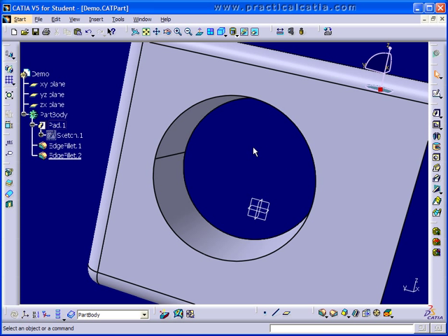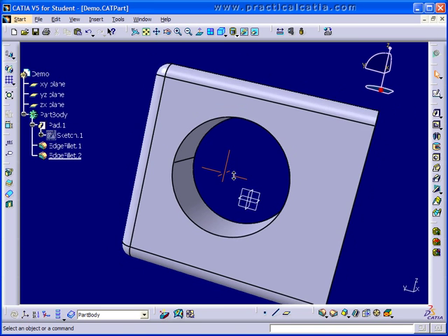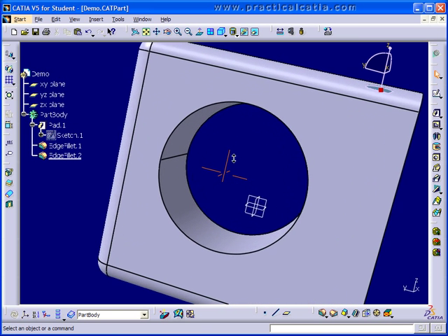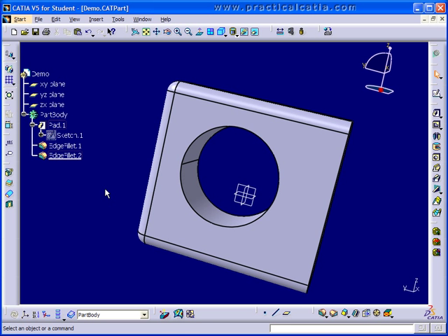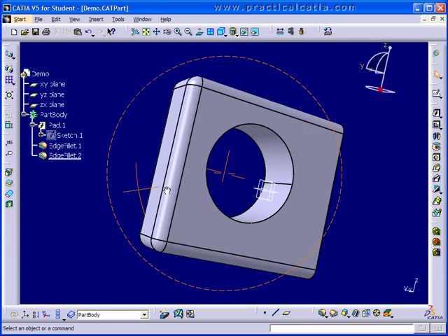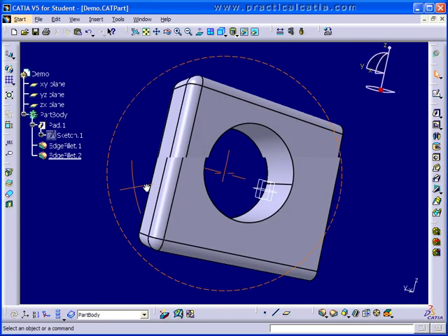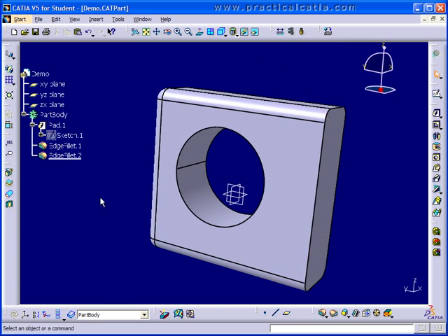So right now I'm going to zoom out by depressing my thumb button and then clicking and releasing the first or third mouse button. And this I'm doing with the thumb button now. I'll do a rotate now by depressing the thumb button and then depressing the first or third mouse button, holding both of them down, and then do a rotate. I just happen to find this a little bit easier to do than trying to push the buttons on top of the mouse. So if you happen to have a 4-button mouse that you're using, go ahead into the software that came with that 4-button mouse and program the thumb button to be the middle mouse button, and you can do this as well.